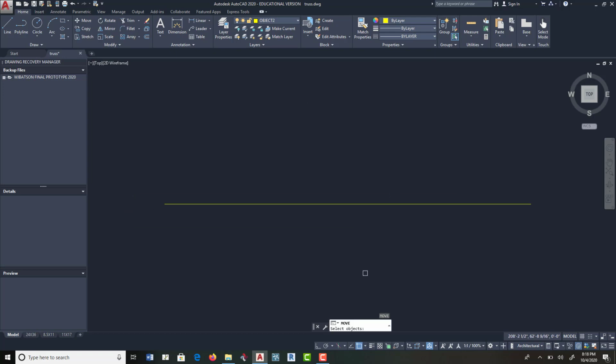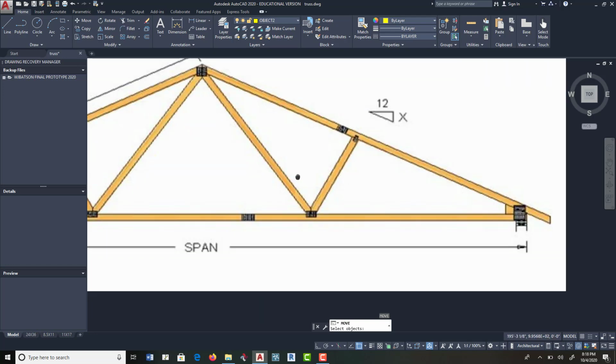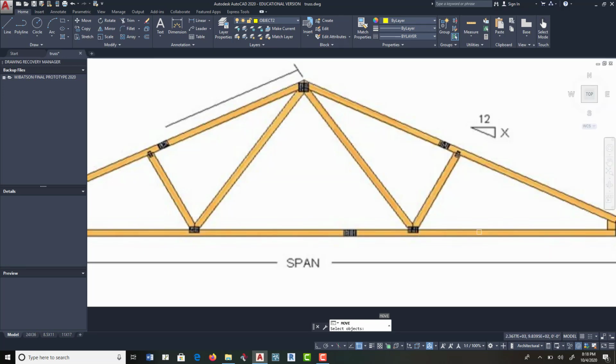So now that's 24. Now, all of these webs, these are chords. There's 3 chords, the bottom and the left and the right. Those are chords. And this W symbol, these are webs. But they're all 2x4 pieces. And if you're going to span up to 40 feet and things like that, then this bottom chord will be a 2x6. And the top and the left chords will be 2x6, but still the inside will be 2x4.